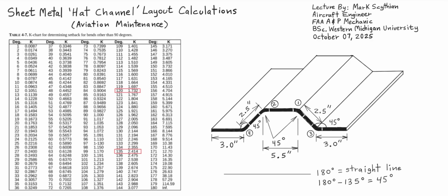Then we have to isolate the flats from the bend allowance structures, but then the working finish length, including the projection of the setback across the horizontal, and in this case the diagonal planes, is the difference between the finish length, the mold length line, minus the setback value, so that will yield the flat.